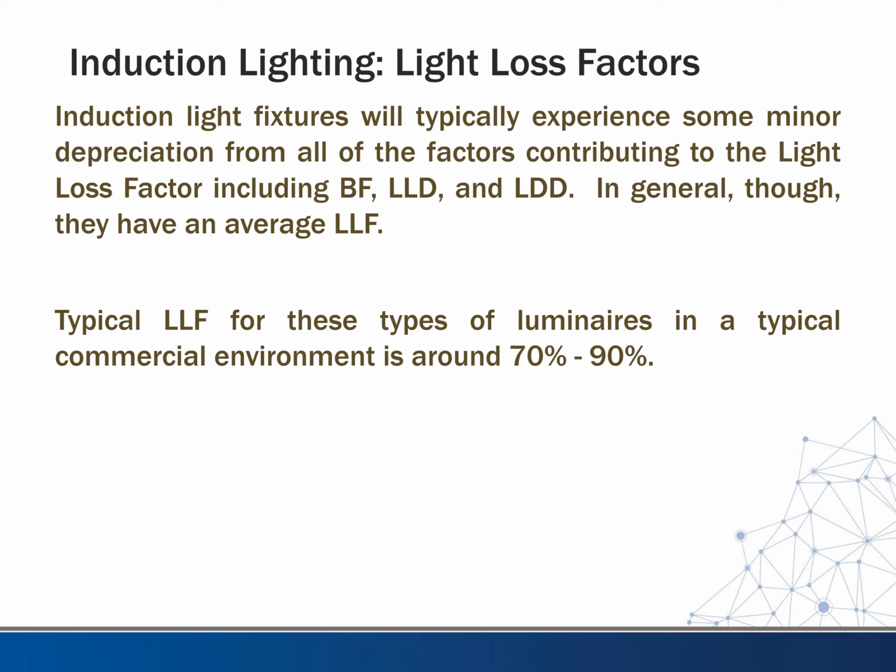Induction light fixtures will typically experience some minor depreciation from all the different types of contributing factors to the light loss factor. All said and done, they're usually in the range of anywhere from 70 to 90%.